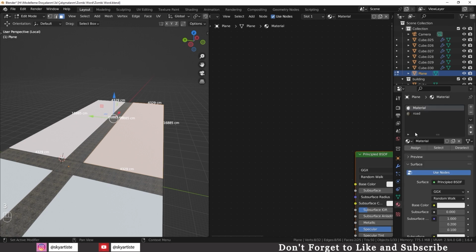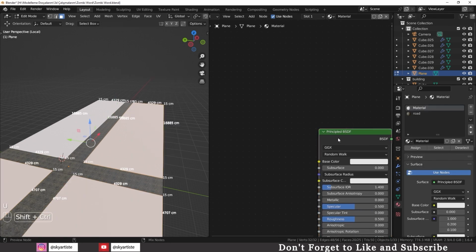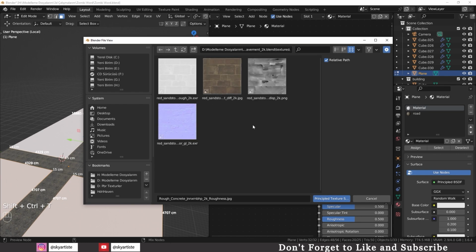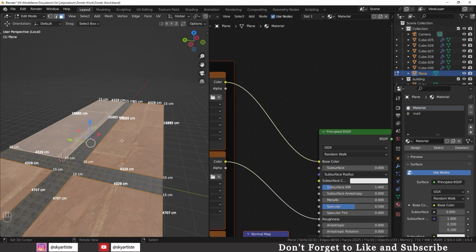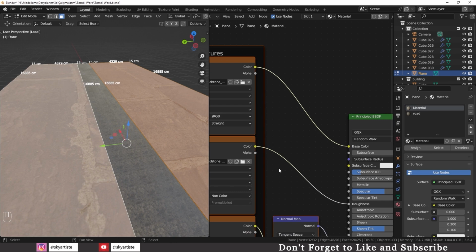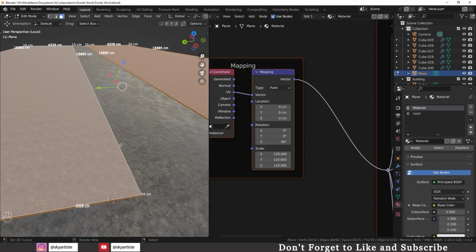Now we are adjusting the texture of our pavements. Again, we assign a UV map by calling cube projection. We make principal shader connections. From the UV scale section, we perform the scale process until it reaches the appropriate dimensions for our scene.